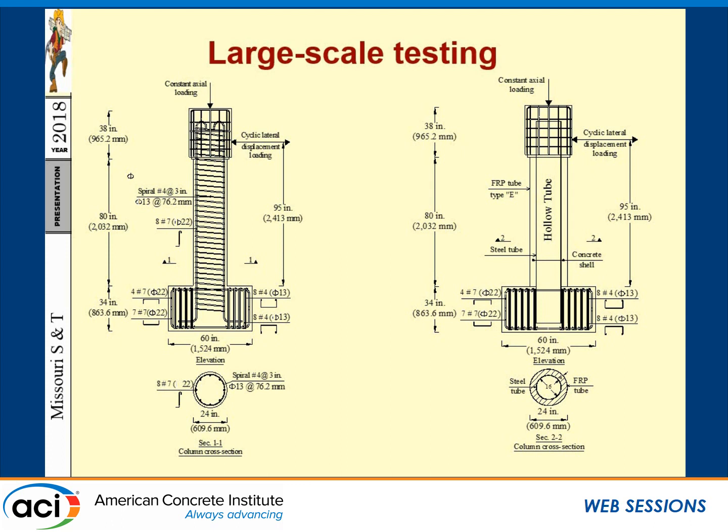So we have a vertical reinforcement of about 1 to 1.2%, and then we have spirals. Well, in Missouri, we don't use spirals a lot, so this is the only thing that we do extra over here. We use a spiral on this column. Missouri just uses regular hoops. And then we tested another set of columns over here with a new column.